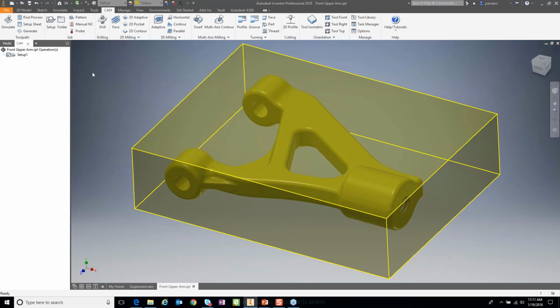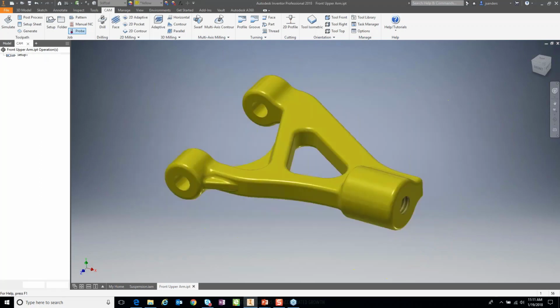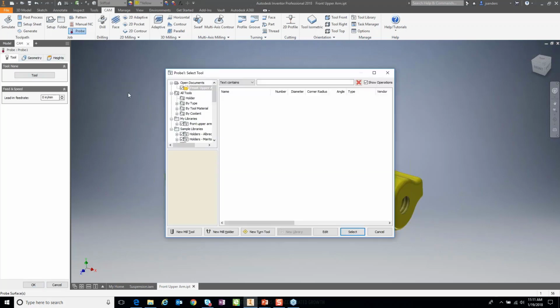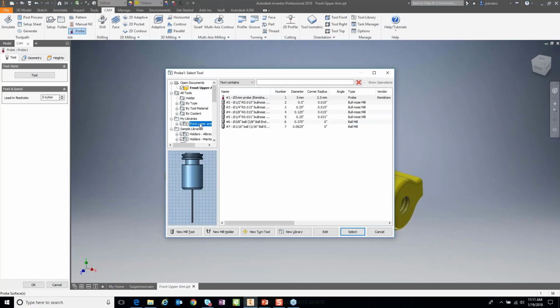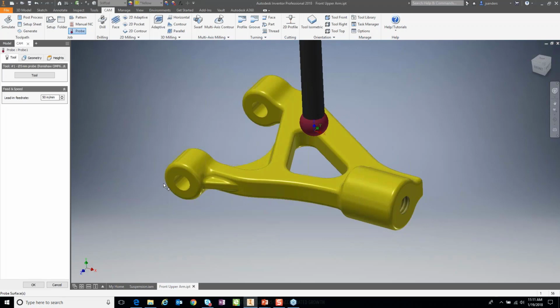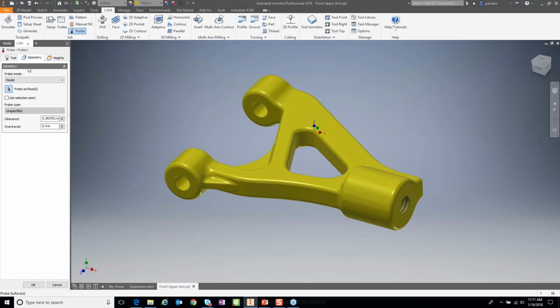The first thing I want to do in the machining setup is use a touch probe to quickly update the part 0 based on not only the rough part position, but exactly where that goes. So as I begin the command, we'll see the same common tabs again. And I'll start by going to the tool button, and working from a tool list I have for this, we'll select the probe that we want to use. So we've selected that Renishaw touch probe, and now we'll tell the software what we want to do with it.